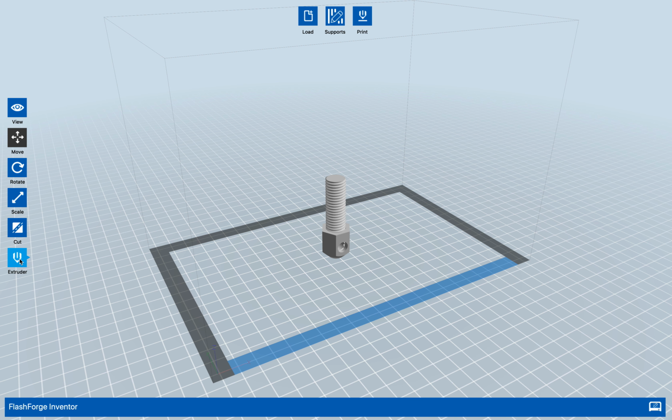And the last thing is this one called extruder, which one you're choosing. And once again, we're always going to be using the right-hand extruder. Don't check the left-hand extruder because we actually don't use that on the machines. It's to do with the plastic and it getting brittle and so on.